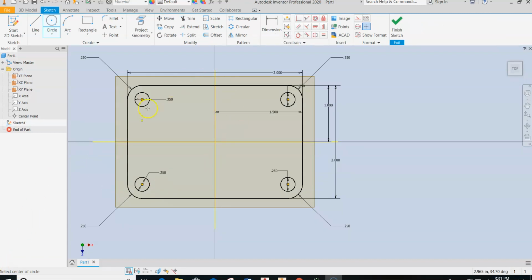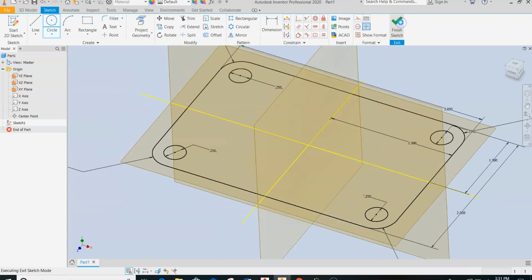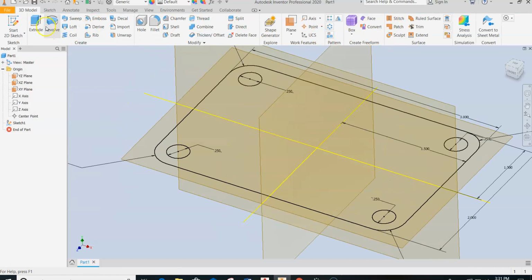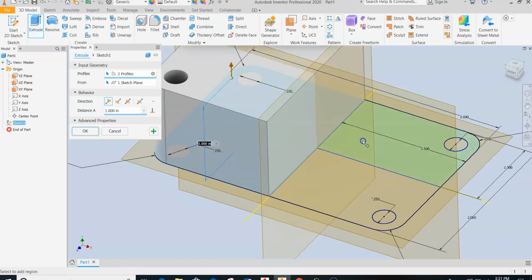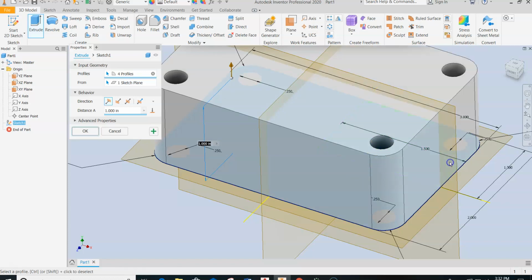So sketch up the base, create the 4 holes, and use the fillet. The fillet and the circle, or the hole there, share the same center point. So using that center point, it's easy to locate those 4 holes. Once you finish this, let's extrude this base up 0.75, and I'm going to click inside each one of these planes here and get all of that extruded up 0.75.